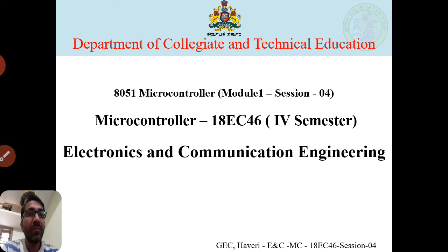initially we have seen what we mean by microcontroller. Basically it is an IC which is used in embedded systems to control operations. Then, after knowing what the microcontroller is, we looked at what is inside the IC and what it consists of, which are the blocks, for example CPU, RAM, ROM, timer circuits, control circuit, all those things. We have seen the block diagram, and inside the block diagram, what the internal circuit consists of: registers, register map, all those things.